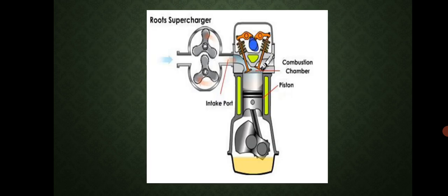At high altitude, since the air gets thinner, the need for a supercharger increases, as it compensates the air intake by forcing relatively denser or heavier air into the cylinder during the suction stroke. Since the supercharger increases the pressure, the engine must be able to sustain higher forces, and the fuel being used must have better anti-knock properties.